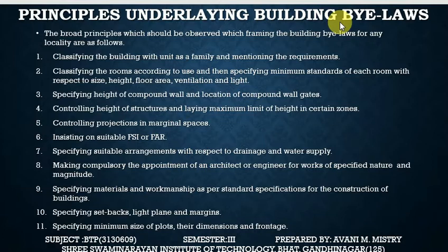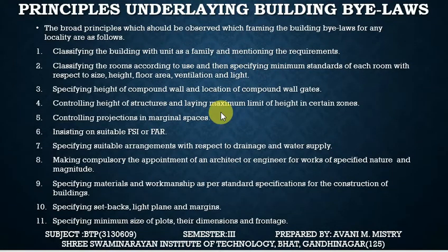Then principles underlying the building bylaws. The broad principles which should be observed while framing the building bylaws for any locality are as follows. First, classifying the building with unit as a family and mentioning the requirements. Classifying the rooms according to use and then specifying the minimum standards.